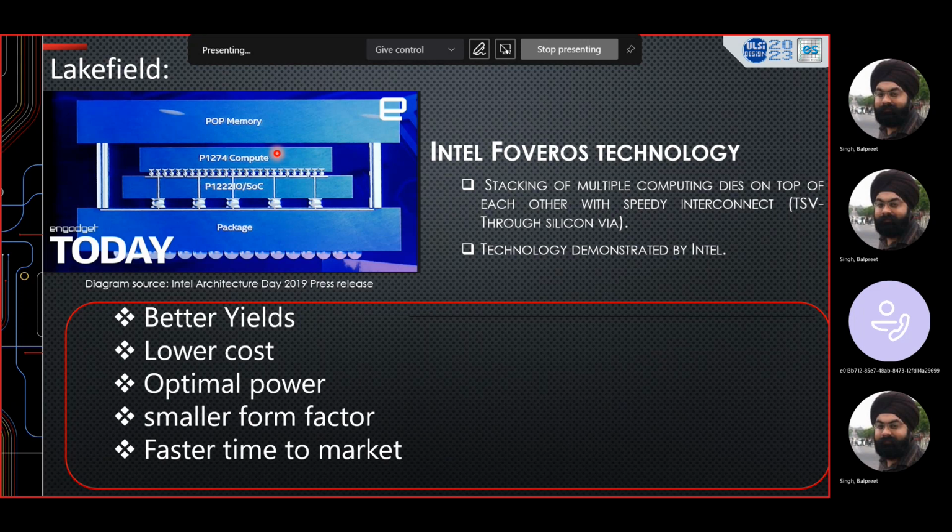So you don't see that kind of a problem for the digital circuitry. For the analog circuitries, you have to be a little careful. You have to do some 3D simulator. So if you have a complex signaling which goes for a couple of Gbps, those few specific lanes, also based on our studies, we have seen not much interference, but you have to do the study based on your use cases and then take the call. But pure digital, not a problem.